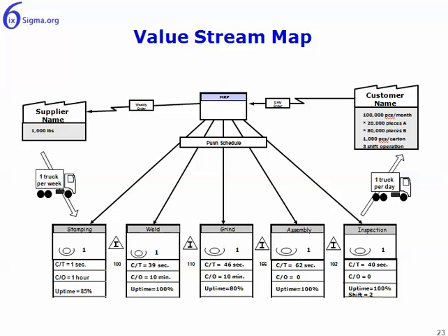And we haven't looked at value stream map yet in the program, so briefly then, we have the process steps that are under consideration or under study, and at each step we want to collect what we believe is relevant information. So it might be the cycle time of the step, maybe the changeover time, the uptime, it might be the defect rate at each step, and so forth. We also want to collect perhaps the queue times between steps, because again, our big Y is lead time, which is the overall time to go through the entire process, and we want to understand what's contributing to that lead time at each of both the process steps and then the queue times as well.